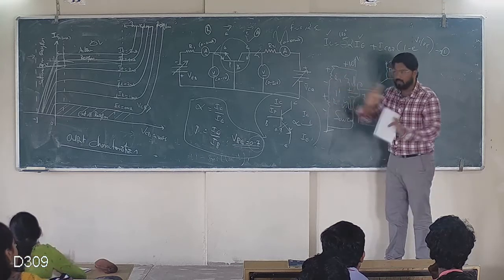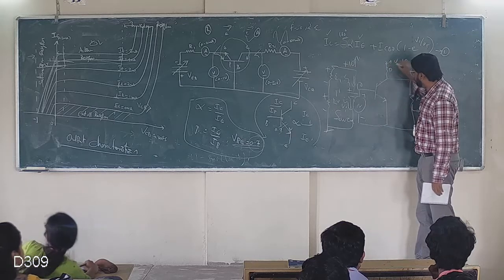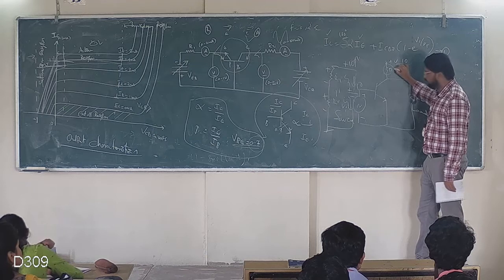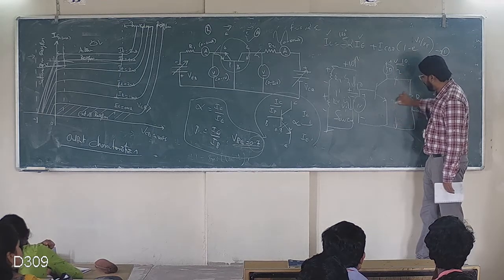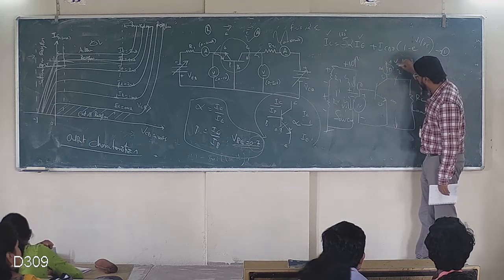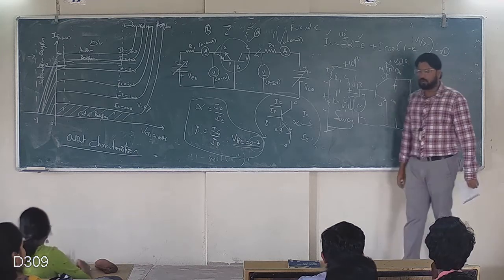R1, R2 are equal. Now the same concept: let's say the voltage given is 10. What is the drop? Let's say 2 volt is taken across. What is the remaining? The remaining should appear like this, right? This is collector, emitter, resistor. So 2 plus 8 equal to 10. That is called Kirchhoff's voltage law.